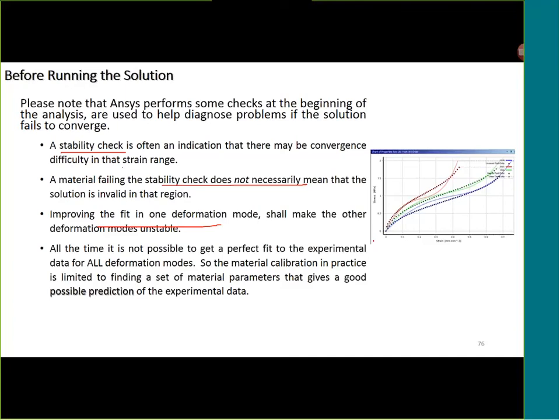There are some places where you have to compromise a little bit on accuracy but make your material model stable, so that you can get more insight about your product behavior rather than looking at the exact numbers, whether the stress is 2 MPa or 2.0 MPa. That is not very important oftentimes, but you need to really understand whether that piece of material is in tension range or a compression range. That is possible by compromising a little bit on accuracy, but it may not be possible by making your material unstable. Okay.